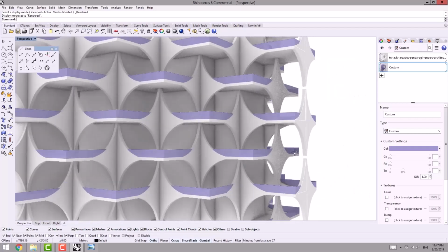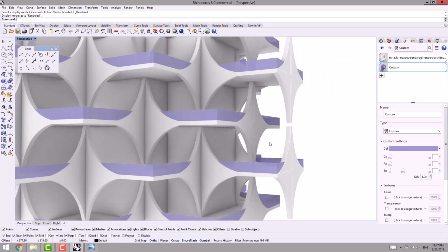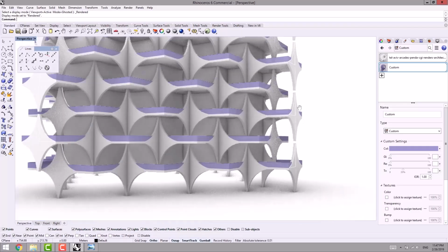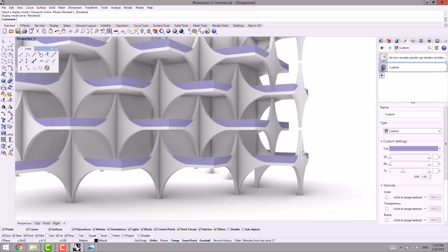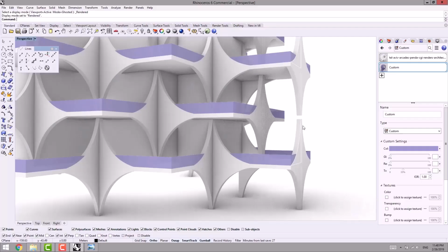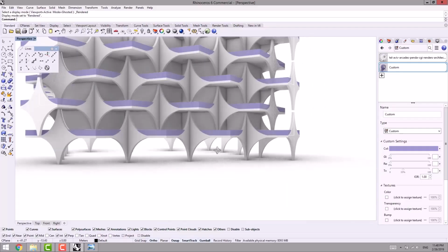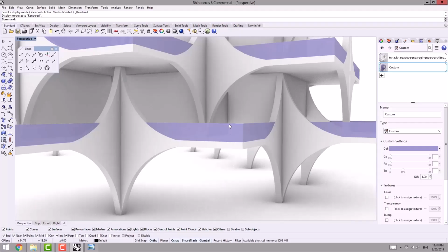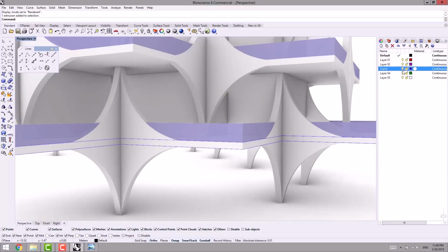And there is a gap here because we considered the distance 3 meters and 60 centimeters, while we had 30 centimeters for the thickness of the floor. So if you want to model, you have to consider the first column 3 meters and 90 centimeters. Okay, now we can do more here.